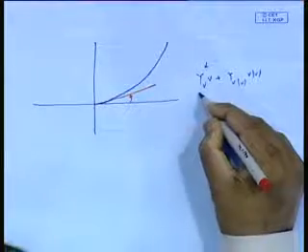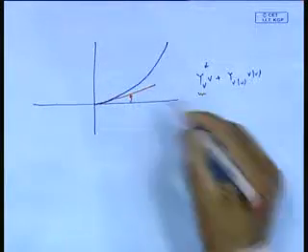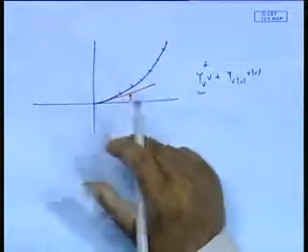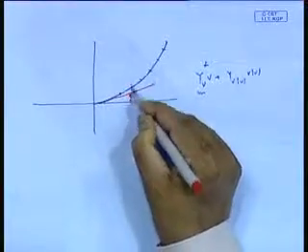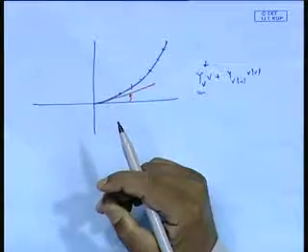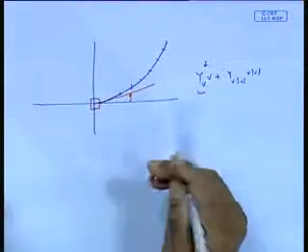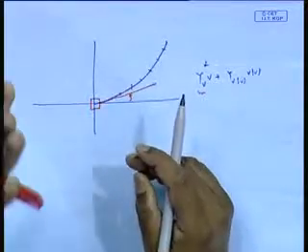So, if I took only the linear coefficient in a measured fit and used this for finding out my stability, I may find out the ship is unstable with C negative, but actually the ship may be stable, because you are trying to tell the force is more, actually the force is more. You see, these things are very important for you to understand: linear derivatives give you only the behavior at this point, but a directionally unstable ship with the control not working does not mean it is going to be unstable.